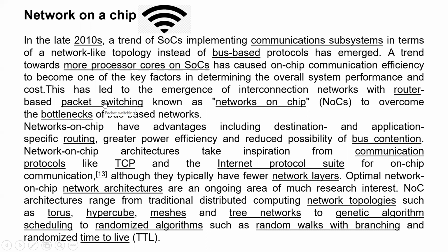And as the trend of including more processors on system on chip was introduced, the communication efficiency between the various modules present in the SoC became a concern. So the traditional bus-based architecture is replaced by a system called network on chip, which allows intercommunication between the different modules by using router-based communication called packet switching.